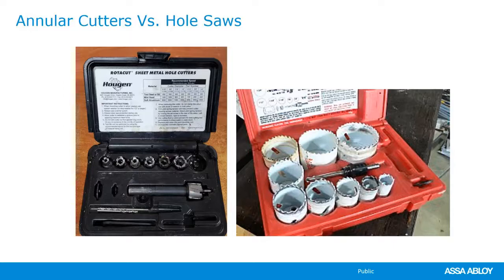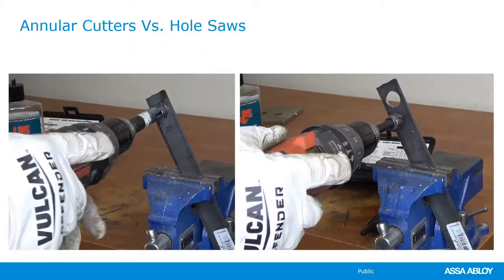But for door and hardware installation, I really prefer the annular cutters, and there on the left is just one particular brand, and they call them a Rota Cut. They're also called by another brand, Rotabroach, and they are designed for cutting sheet metal, and they do just an amazing job at it. So here we're going to compare and contrast that. The top hole I cut with a hole saw, and the bottom I cut with one of those annular cutters.